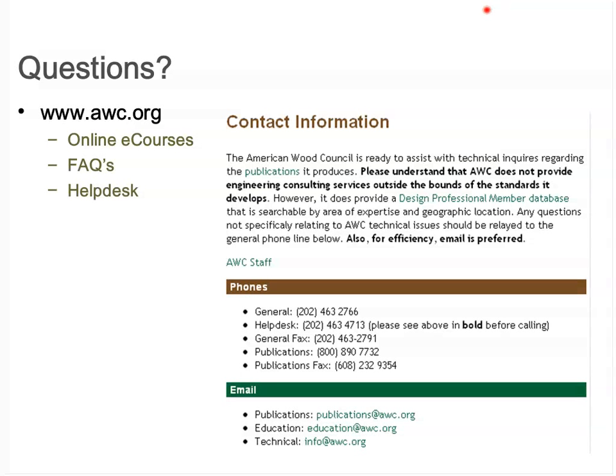Okay, yep, I'd like to encourage everybody to submit your questions at this point for Buddy if you have any, and he'll take them at this point. Okay, another coming through. Yeah, another answer for the deflection limits: L over 240 for brittle finishes, L over 600 for gravity loads on brick. Huh, that's gravity loads on brick. Interesting. That doesn't account for the lateral loads.